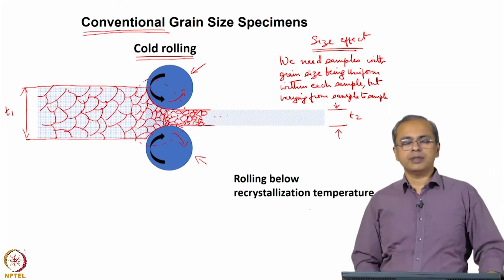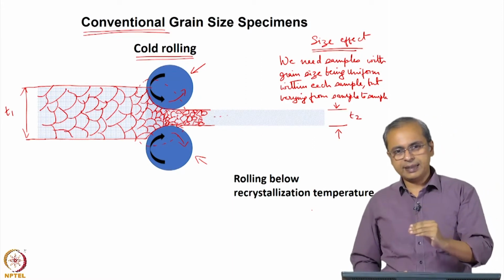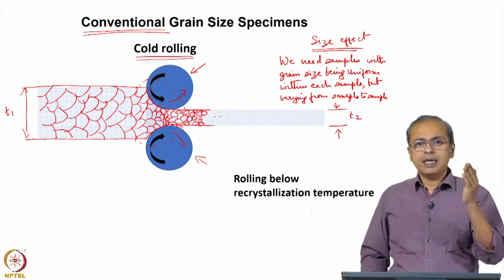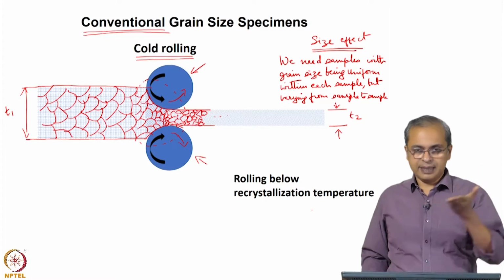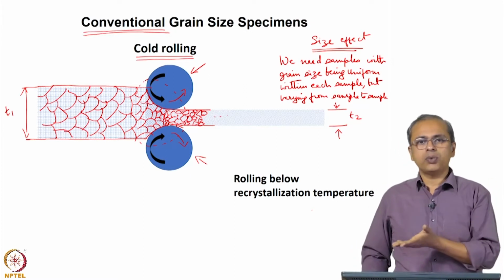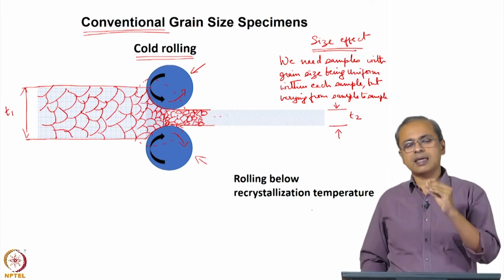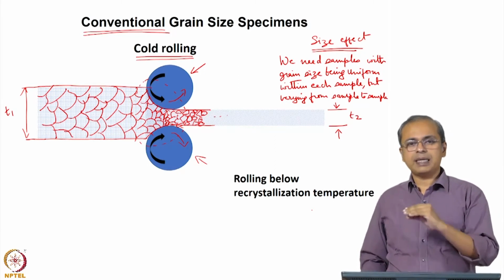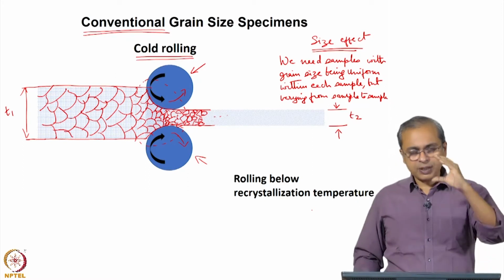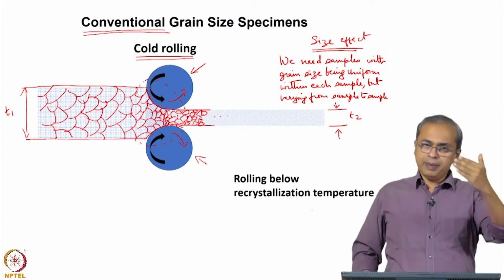So, this is a typical rolling process, and there are some restrictions. This is a schematic, so it looks like you can take a very thick material and roll it down to a very thin material. In fact, it is true that you can eventually do this. Normally you will not do this in a single pass, each time it goes through it is a pass. You send it through and you get it out to the other side. There are restrictions on what you can do in a given pass, given the stresses that are involved, given the kind of behavior of the material and so on. If you want a nice smooth sheet coming out, there are some restrictions on how much you can reduce. So, reduction per pass, there will be some restrictions. Within those restrictions you can do it, but you can continue this repeatedly.